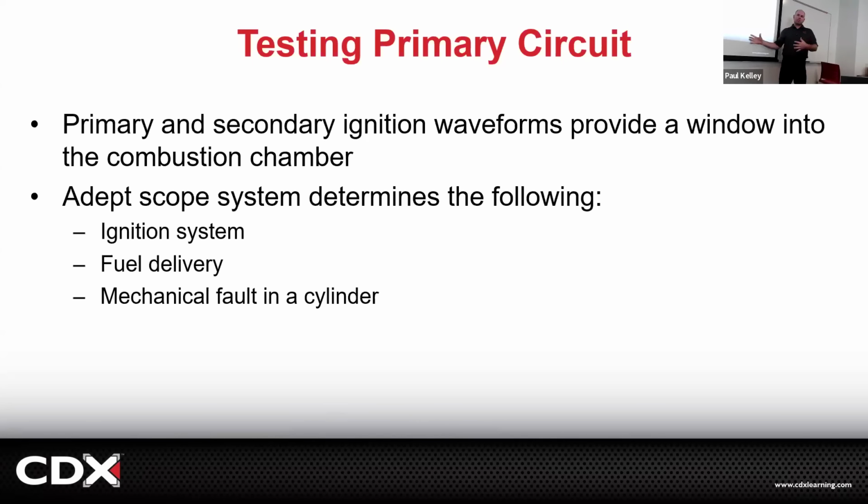I mean, they'd bring out the big old Sun ignition system tester, a big old oscilloscope, but it wasn't even a digital storage oscilloscope. It was mechanical, and they'd probe it up on a bunch of stuff, and they could look at the waveform and say, oh, that cylinder has low compression, or that's a lean air-fuel ratio, or that's a rich air-fuel ratio. I mean, pretty awesome.